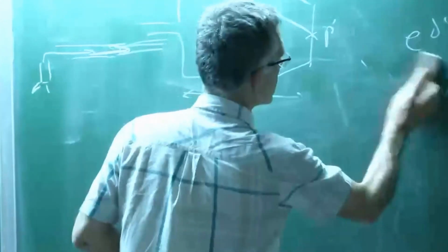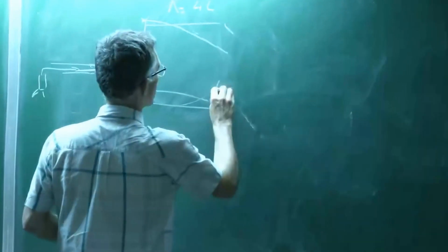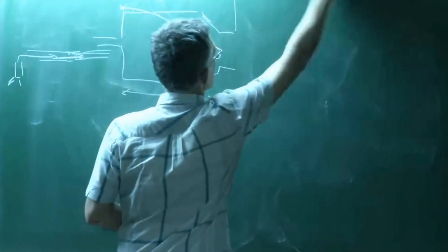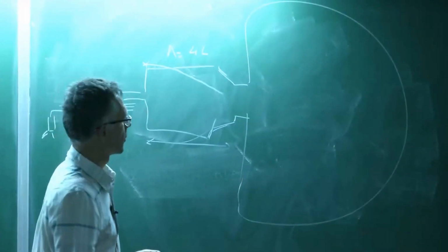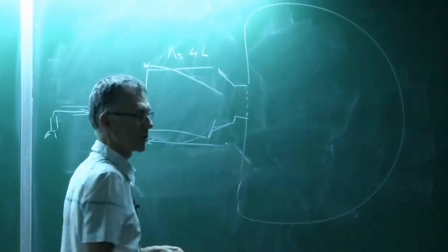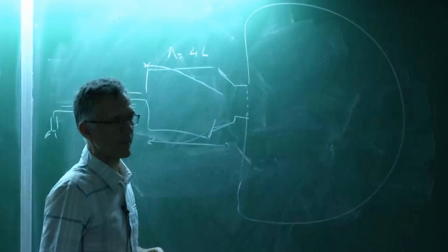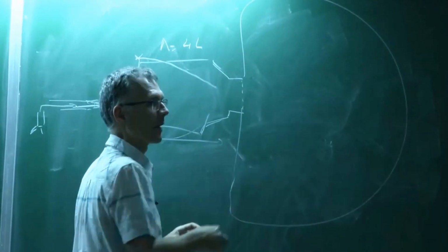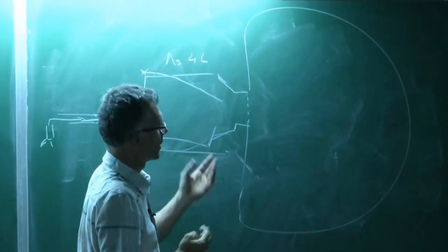We know that we have to be very careful about boundary conditions. So we just remove them. We mesh the atmosphere. That's how we do it in AVBP. So in this zone here, there is no boundary condition. The boundary condition is far away, and in this way, there's no problem. Every time you compute these things, it's better to put the boundary condition far away, so you are sure that you do the right thing at the outlet. That's an easy way.